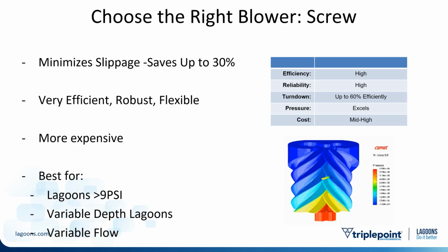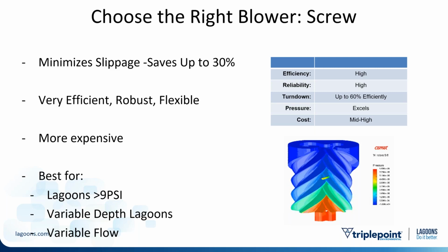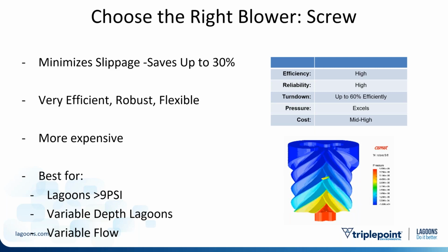But because it's a newer, more advanced technology, it is more expensive. So if you're going to use a screw blower, you want it to be in a lagoon system that's deep or has a lot of pressure. They thrive usually above 9 psi. If it's above 9 psi, these are pretty much going to pay for themselves.